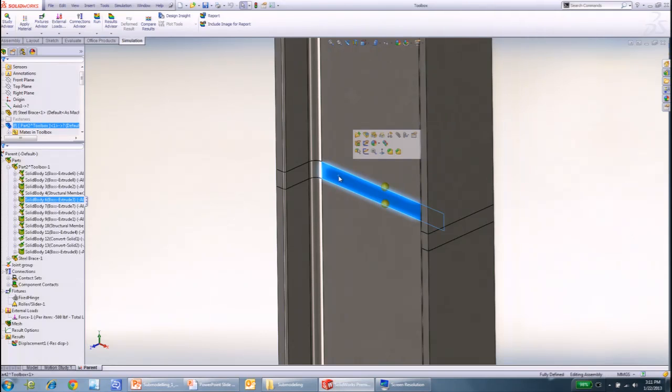So I have a small band which I'll make a solid. The key here is you have to run the complete beam model and this model to make sure that displacement patterns are very similar. With a small beam, it is okay in this model, so you can make the same assumption. This is almost like a cheat sheet to say, okay, now transfer the displacement fields on the solid. Then in the submodel, I'll connect the details to that small solid because it transferred all the displacements.